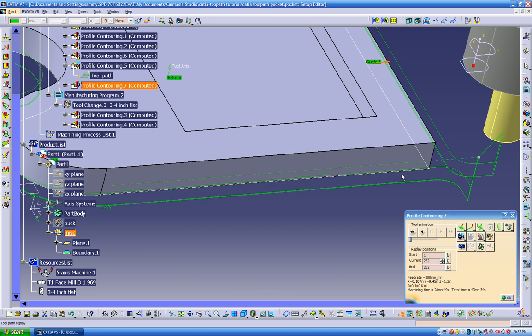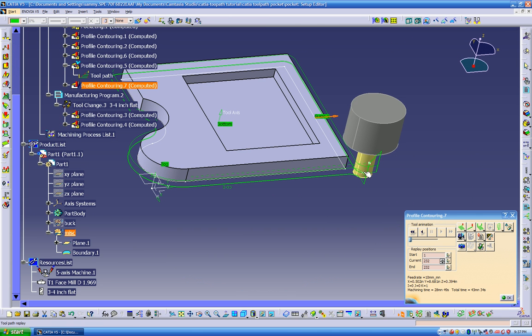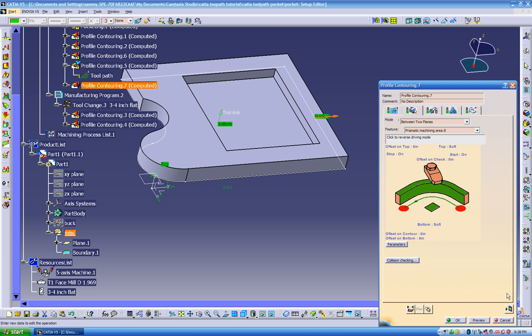But you can put limiting. If you don't want the tool to start on the edge of the part, for example, you want to bring this tool on this point, or you want to start over here, what we can do, we can go to this option over here. So we have two entry points. We got the entry and an exit. You see the arrow right here. Now if I go to the exit point, knowing that this is my entry, watch what's going to happen.